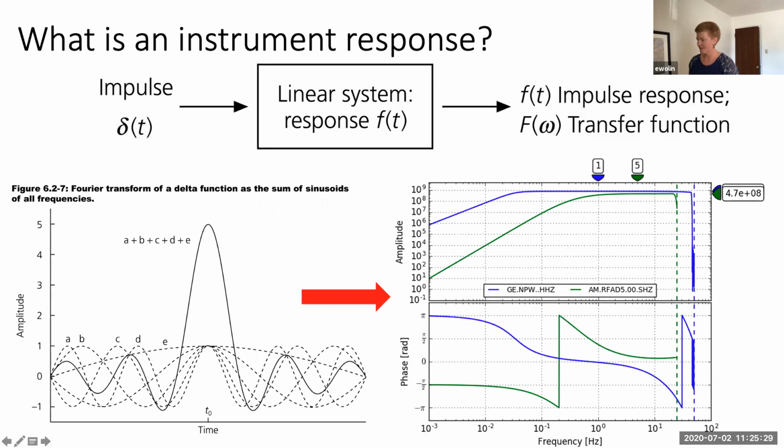Looking at the phase response here, right? So this is the imaginary part of that response. We can see that the Raspberry Shake has a very different phase response than the broadband here. So if you wanted to compare these two signals directly, it's very important to account for both the amplitude and the phase response, because this large jump doesn't actually spike like that. It just wraps around from pi or minus pi to pi. That's going to make your raw signal look very, very different than this broadband curve here.